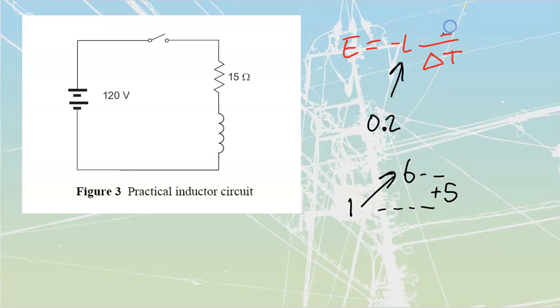That's the change in current. We're going to put that in as being a plus 5 because it's positive and an increase in current. Over top of a time of 20 milliseconds, we write that as being 0.02, like that. So now I'm going to take this one and 0.2 like that. And so now I put it all together inside of my calculator. When in doubt, bracket it out. 5 divided by 0.02 multiplied by 0.2.